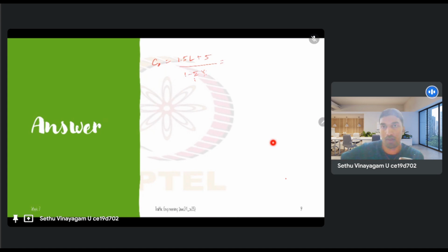Okay, so this we have to take for the whole cycle, right? Not just for each phase. And what is given to us is the loss time per phase is 4 seconds. Okay, and then we have an all-red time that is equal to I think 1 second. So we have 1 second of all red and 4 seconds of total loss time per phase, right? So both of these are per phase, but L is for the whole cycle. So L will be